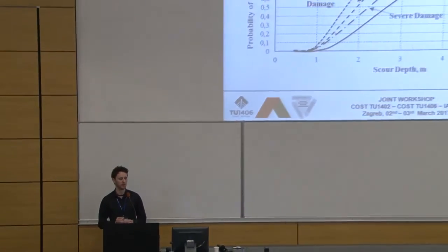But what we have found is, broadly speaking, national authorities who own the bridges tend to implement their own type of systems to design for these. But in effect, it's post-event as opposed to pre-event is how scour is mostly looked at these days. So for old aged structures, generally you're looking at retrofitting it for scour. These design methods, although they're great for initial preliminary design, are not that relevant for assessing an actually existing structure due to scour.